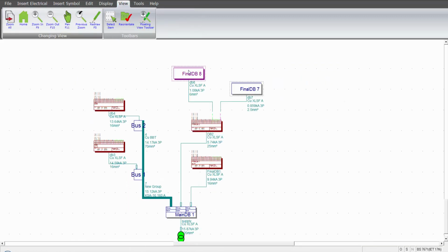So what I'm going to do now is introduce a single phase board. So I'll just move these boards around. What I'm doing is moving the board, and if I click on the horizontal bit of cable and then drag up with the left hand button of my mouse, I can rearrange the cable. So they're quite easy to arrange. You just select the center section of the cable, so it's sort of cyan colour, and then you just move it up and down to suit your arrangement.